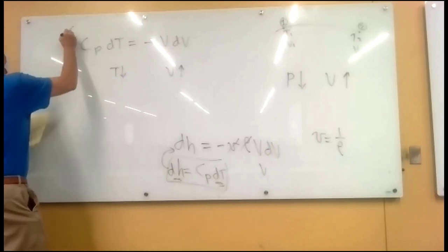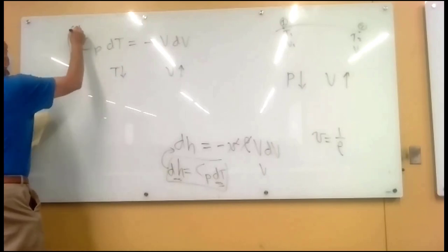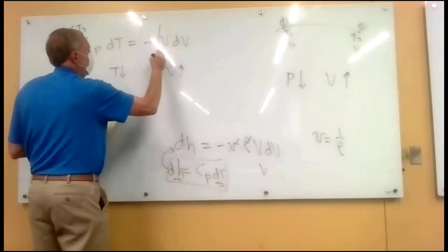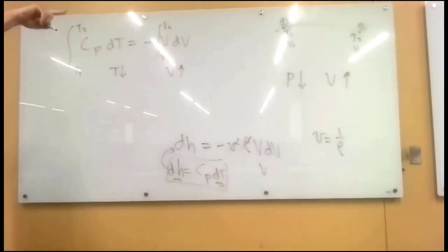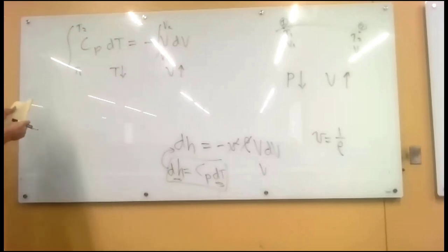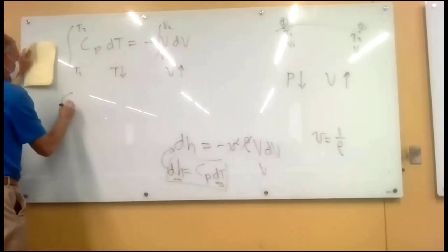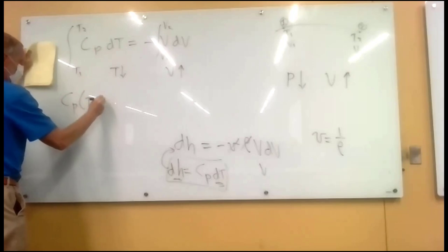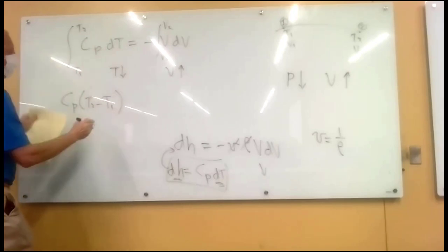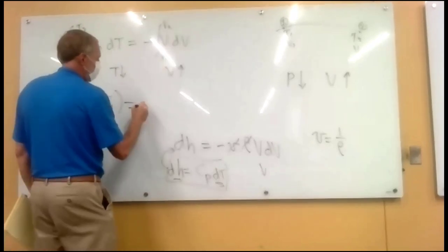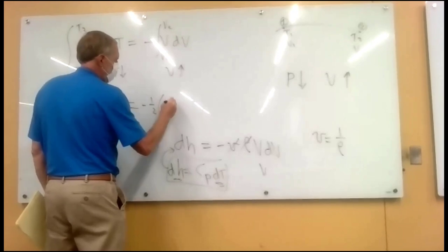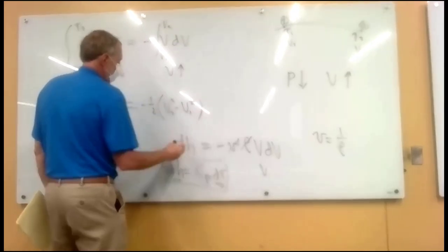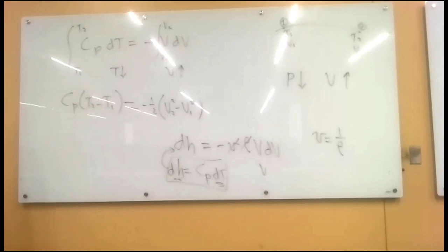All right, so we integrate this along the streamline, which just means we add up all those little increments as we go along the streamline from 1 to 2. This is easy to integrate. dt just becomes t. Plug in the limits. And this becomes v squared times 1/2. So I factored the minus 1/2 out. And that's the equation that I wrote on the board last time.